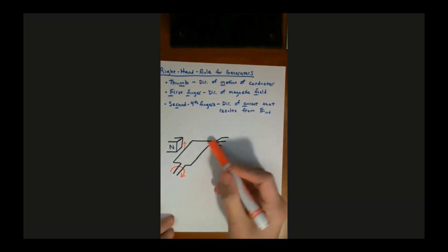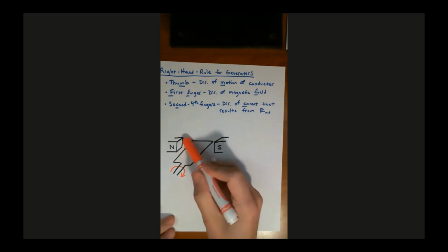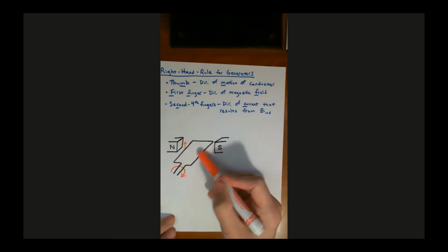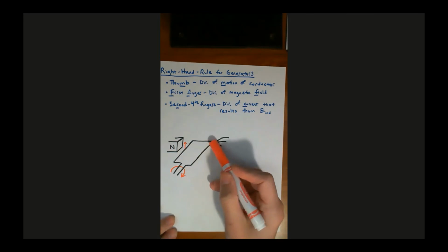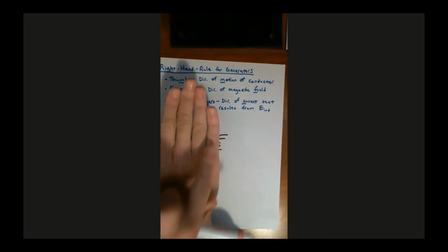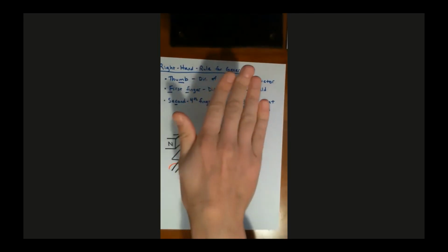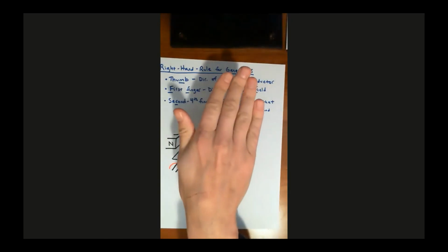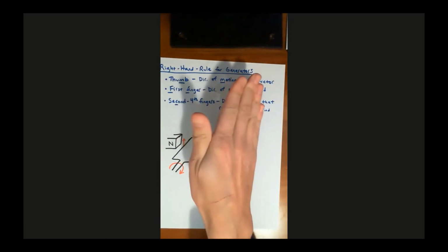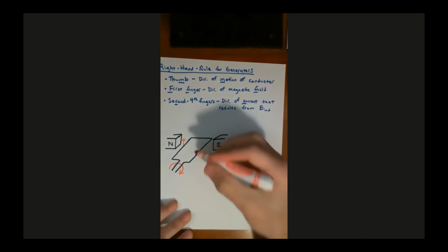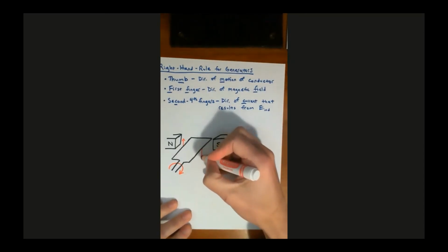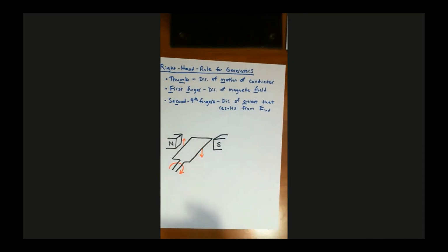Likewise, let's do the other one real quick, because if this one is moving up, then that means that this wire segment over here must be doing the opposite. Now we're talking about like my pinky over here. As it's rotating clockwise, right now my pinky is moving straight down. At this snapshot in time, this wire segment on the right side of the armature is moving straight down.